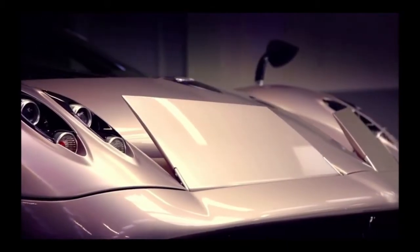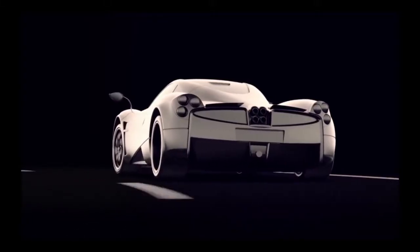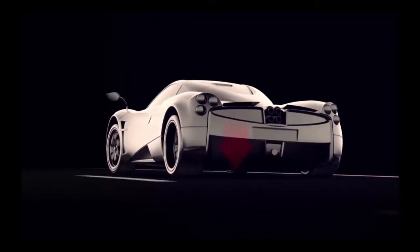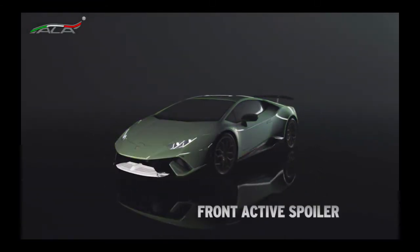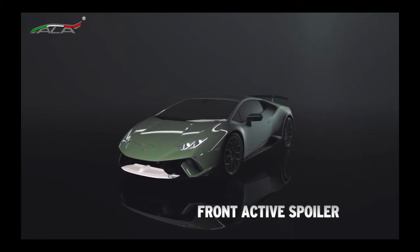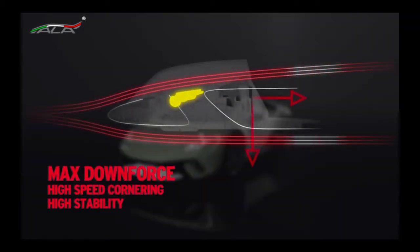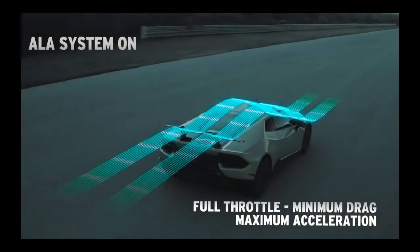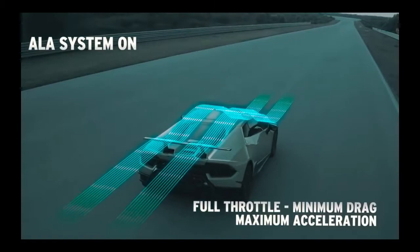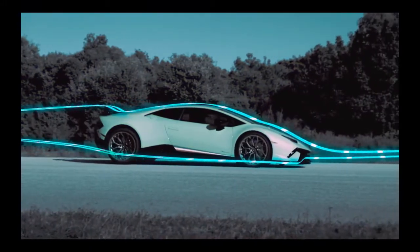An example of an active aerodynamic system is in the Pagani Huayra. The Pagani has 4 active stabilizers which will act independently in order to increase the downforce on a specific side of the car. Another example of an active aerodynamic system is in the Lamborghini Huracán. In this system, there are 2 hinges which will open up, allowing airflow to flow through the car, which minimizes drag and increases acceleration of the car. Inversely, it will close off the ports in order to increase the drag when needed, such as turning around corners.